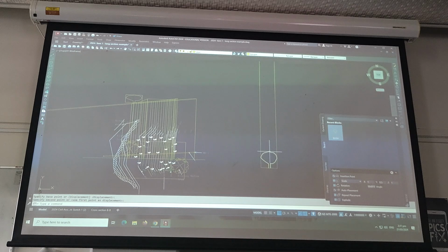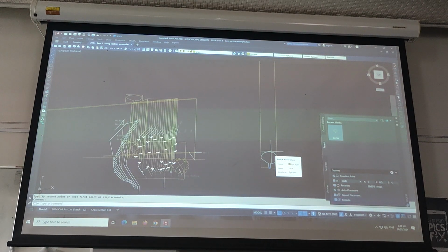Whereas that's the tree that I put on my long section. So the secret that I wasn't doing was adjusting this Y factor down the bottom to 0.5. And I want you to block your tree in from your long section when you're doing your cross section, not for assignment 1, for assignment 2. Right?